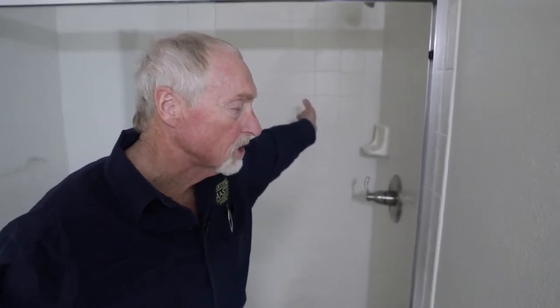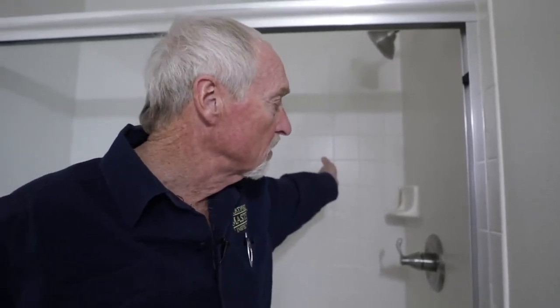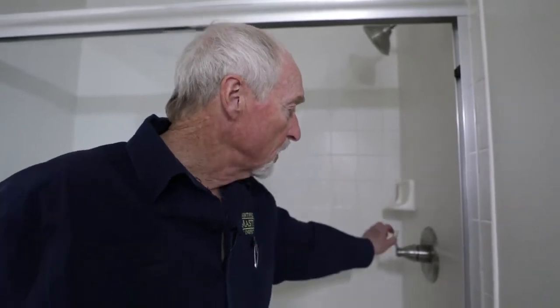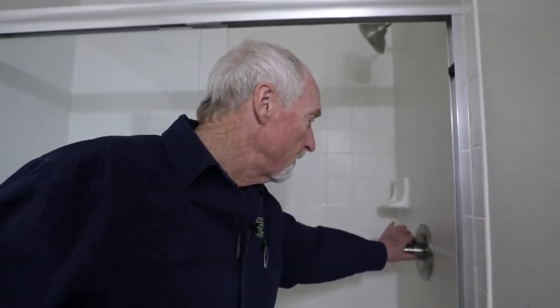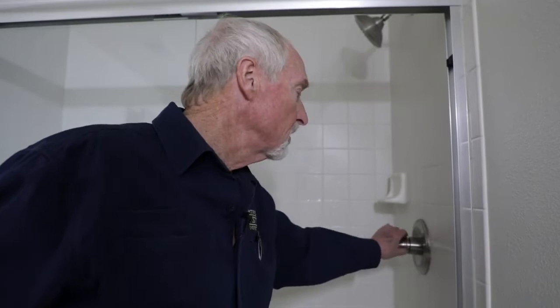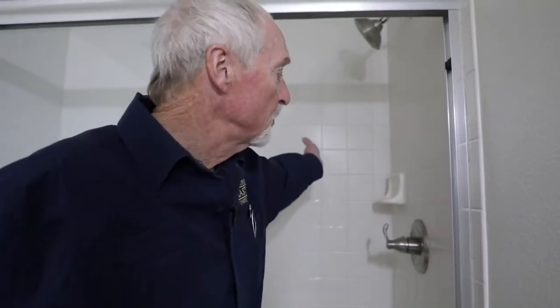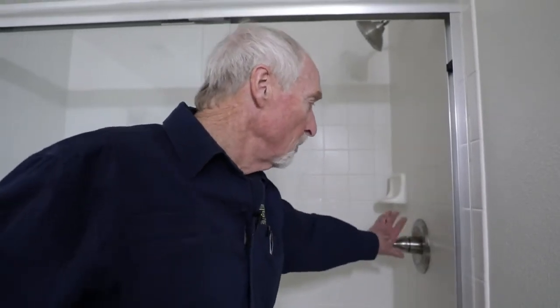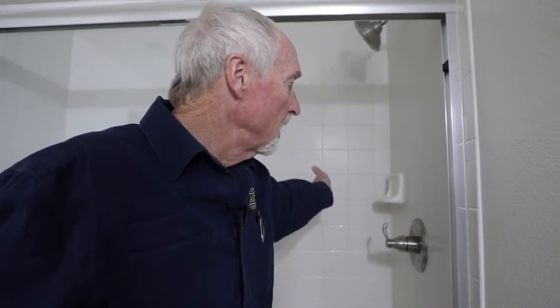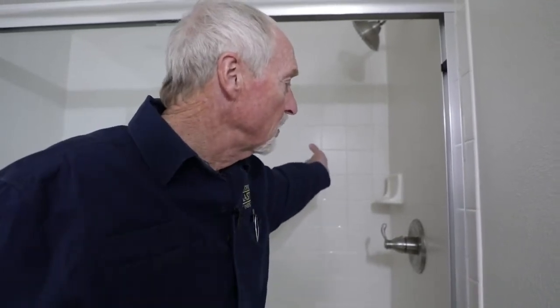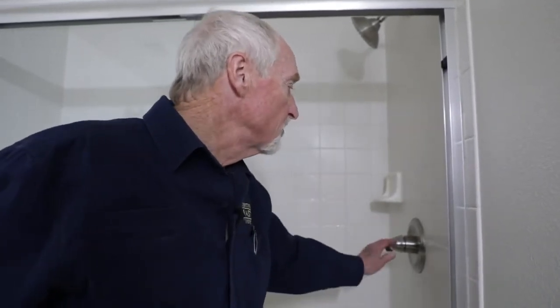If I'm suspicious that it's above that, I will go grab a thermometer and double check it to see what the temperature is. These new fixtures have an adjustment in them so that the water will mix inside the fixture, and you can adjust it so that you don't have it running too hot. That's important mainly for kids. So this one's doing good.